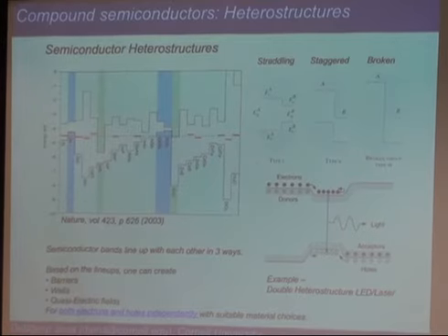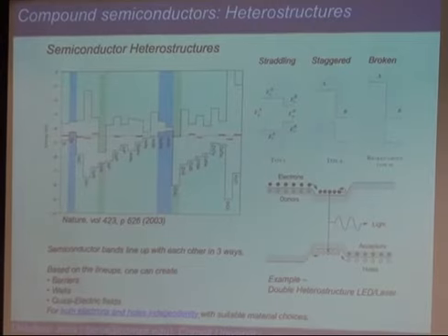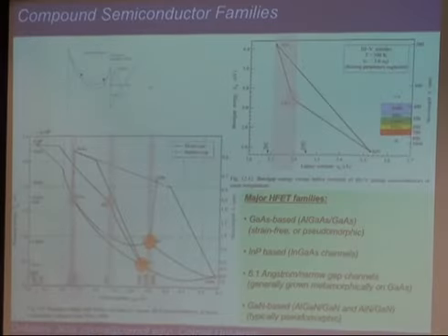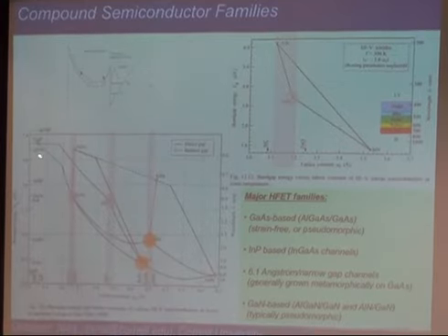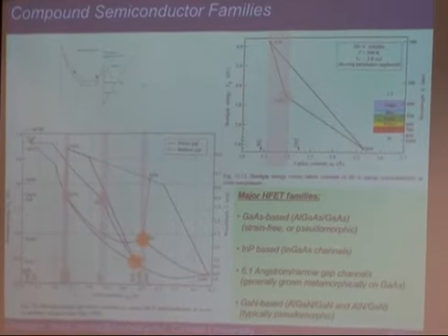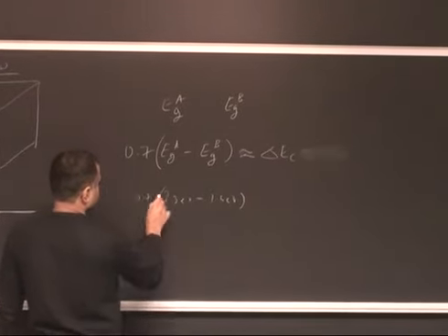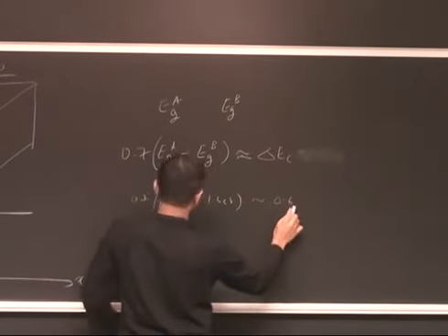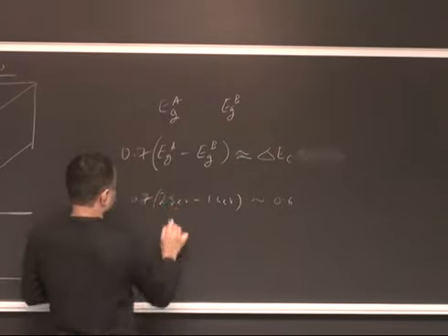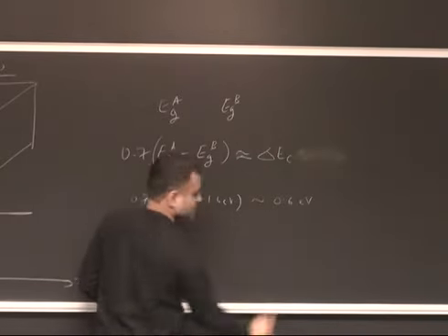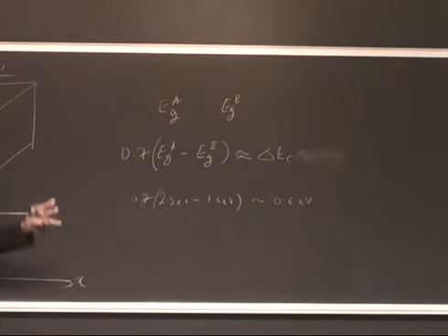Okay, so this is a rough order of magnitude. Let's take as an example aluminum arsenide, which is about 2.3 eV, and gallium arsenide, which is about 1.4 eV. So 2.3 eV minus 1.4 eV is about 0.9, times 0.7, roughly 0.6 eV or something like that, if you choose aluminum arsenide and gallium arsenide.